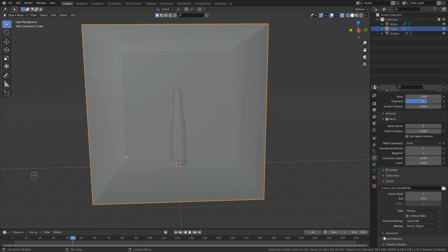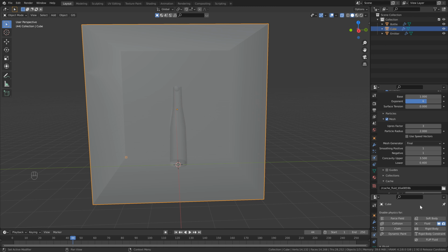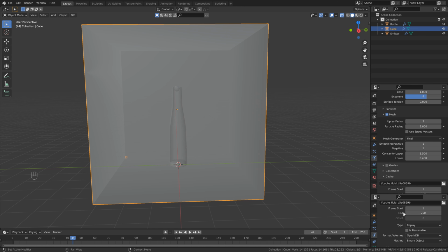One thing that I like to do, since we are going to be making some changes with this, is just add a second window. So head down to the bottom here, just until you see this plus symbol. Then you want to click and drag to open up a new window. Scroll all the way to the top, and you can click this little pin icon, and what that will do is sort of set it in place to wherever you put it. So I'm going to scroll all the way back down till I've got our cache settings here. Now once we go make some changes to our other things, we don't always have to come back and scroll down. We can just have the settings that we need right here.